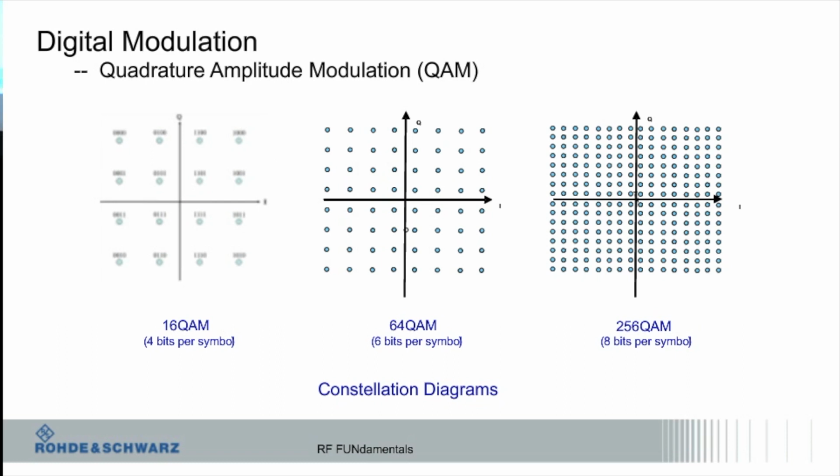So 10% bandwidth on a 10 gigahertz amplifier is difficult. But if I made that a 1 gigahertz amplifier, to get the 10%, it's obviously a smaller number. So usually you'd use a higher carrier frequency if you want a wider bandwidth, because as a percentage bandwidth, it's usually much easier.